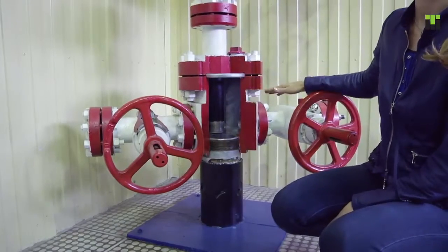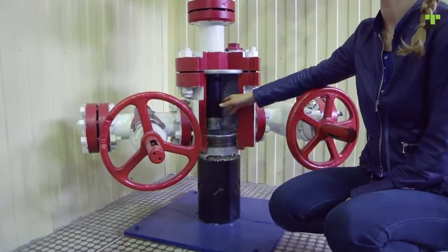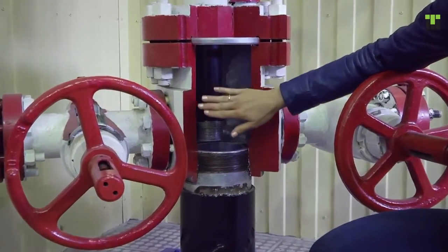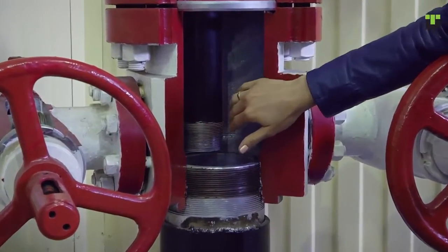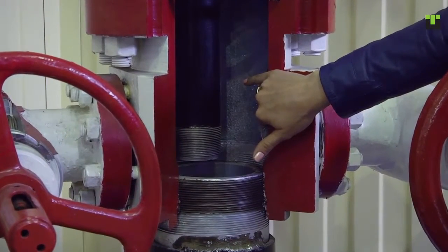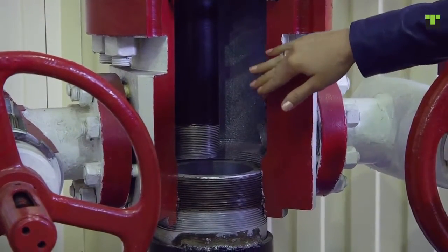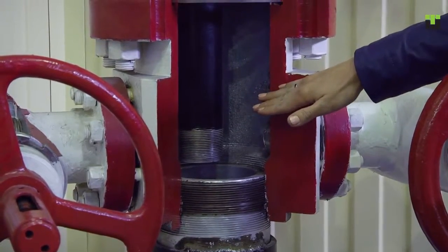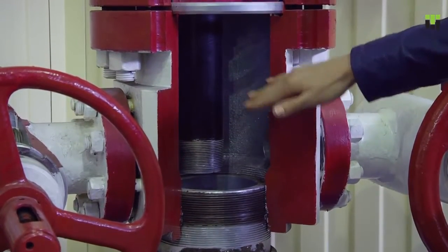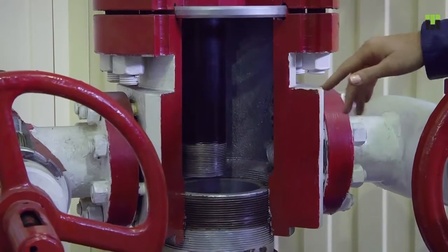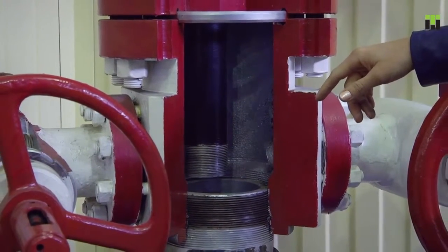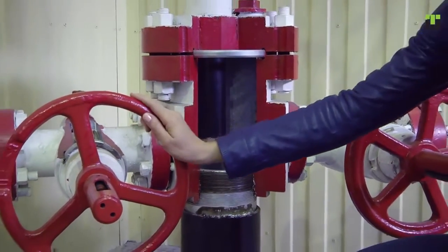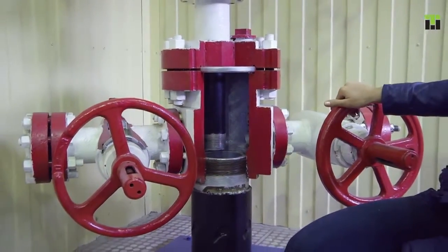Tubing head attaches the flow string or two flow strings. It seals off the annular space between the production casing and the flow string and allows for technical procedures such as well completion, well clean out, removal of paraffin deposited on flow strings, sand removal, well workover, etc. Typically, tubing head is a cross-T with two side outlets and the tube hanger.